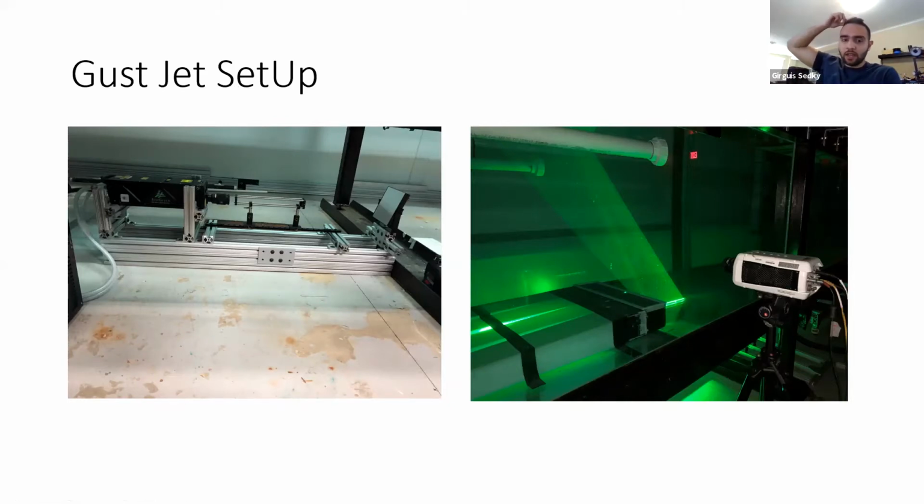Rather than just having a pipe going to a settling chamber with lots of stagnation flow and the water shooting upward, we made the gust generator a lot more streamlined, a lot more like a wind tunnel, with turning vanes, flow conditioners, screens, all that stuff.